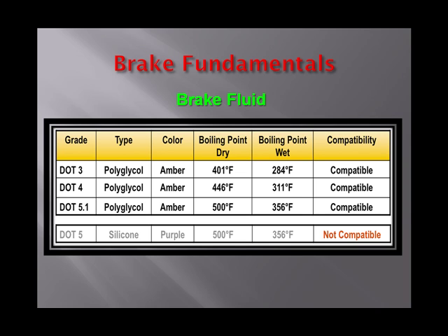This is generally recommended for most ABS systems and power brake setups. DOT4 is a conventional brake fluid with an ERBP of 446 degrees Fahrenheit and a wet minimum of 356 degrees Fahrenheit, and is the most common brake fluid used in modern braking systems.